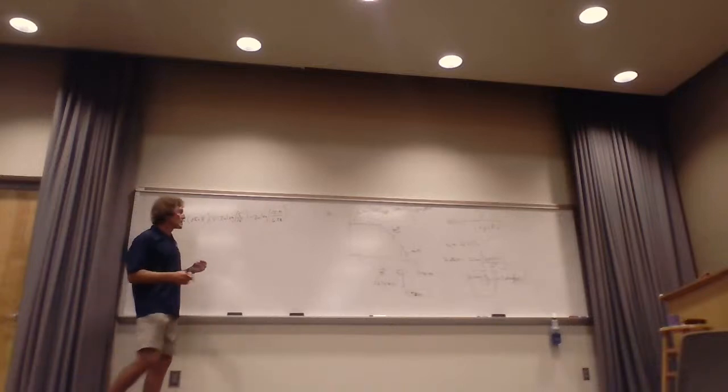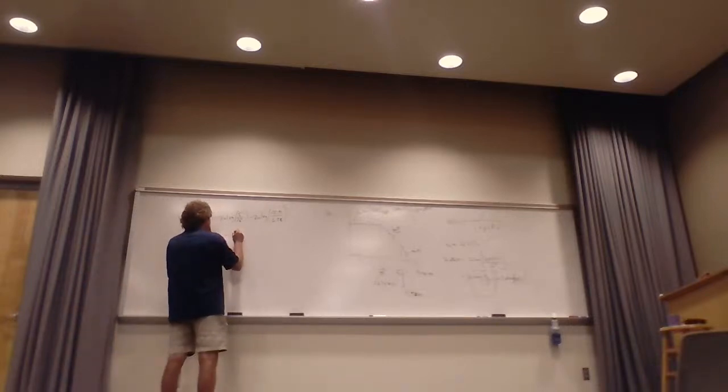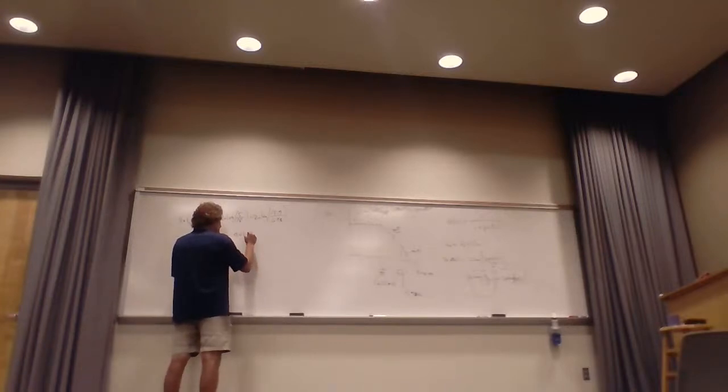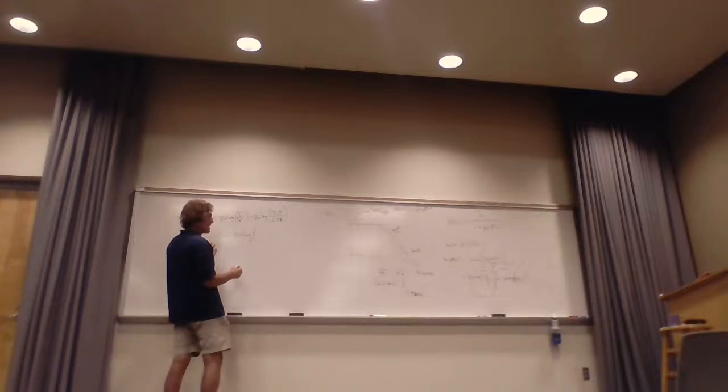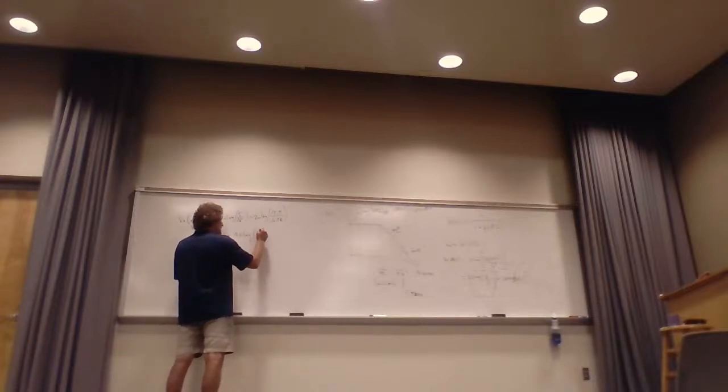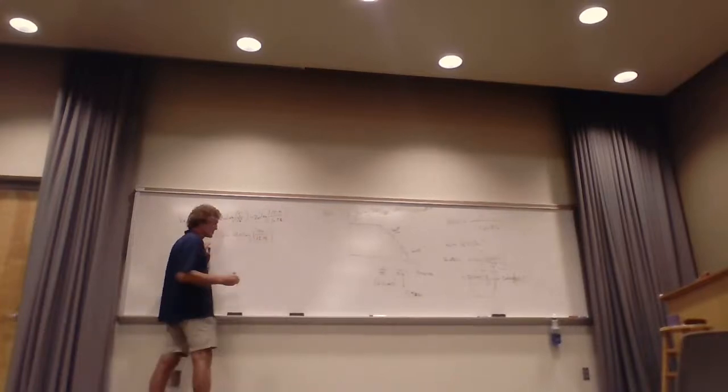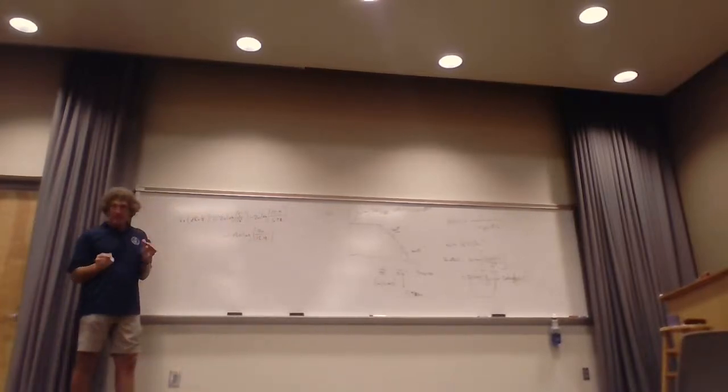And the last part, that's falling off at minus 40 dB per decade times the log. Now it's the upper frequency, or 90 over 15.9 megahertz, correct? Now that's what the source signal spectrum is in dB microvolts at that frequency.